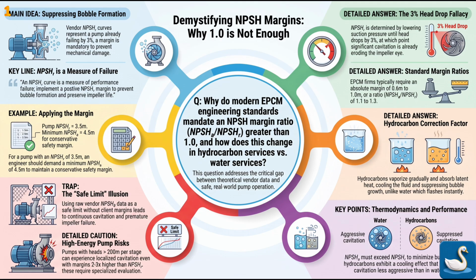Let's begin. Modern EPCM engineering standards mandate an NPSH (net positive suction head) margin ratio, specifically NPSH available over NPSH required greater than 1.0. Explain why this specific margin is non-negotiable, and detail how this structural risk profile changes when transitioning from pure water services to hydrocarbon services.